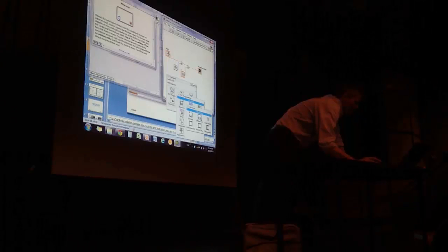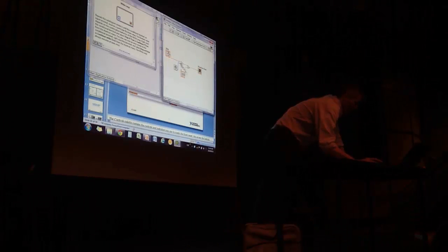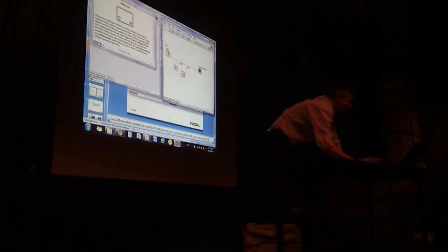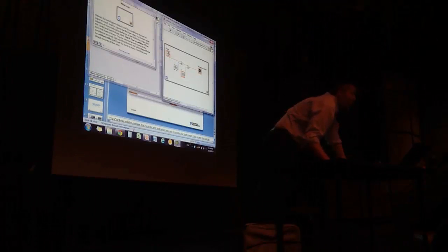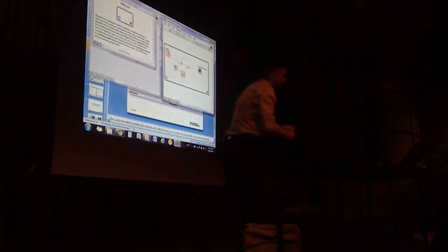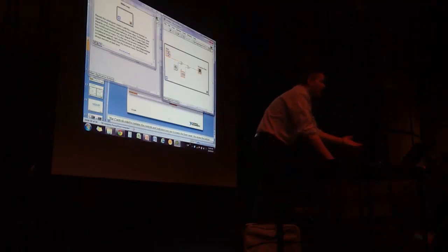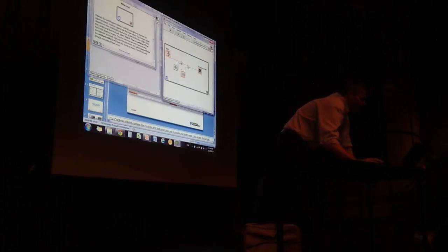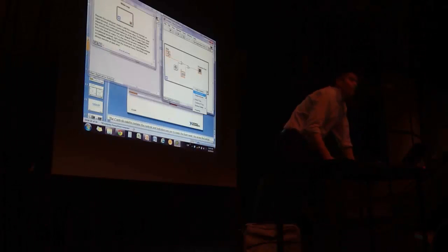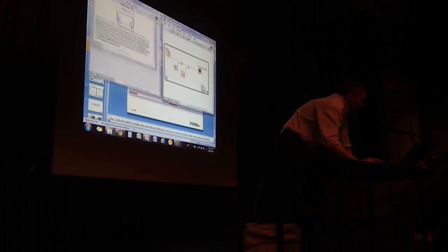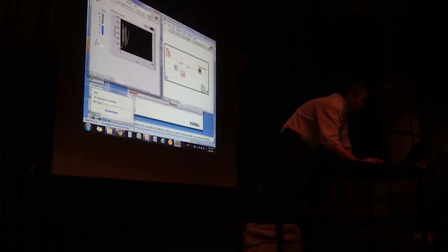To use the while loop, you just select the while loop, and you see that the cursor also changes. I can just drag the cursor around and drop it there. So now I have created a while loop. The only thing I have to define now is when it should actually stop. So what I can do here is create a control as well, like we did before: right mouse click, create control. And what we should have here now is the stop button.